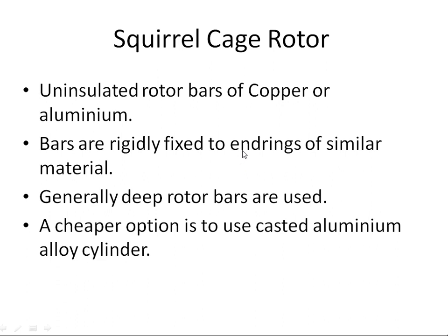What we do is that we heat the end rings, which have holes of the same diameter as the bars. Due to heating, the expansion of the end ring takes place, and we slide the bars into the end ring holes, and then we allow it to cool. This is known as the thermosetting process for setting the end rings. So end rings are rigidly fixed to the bars.